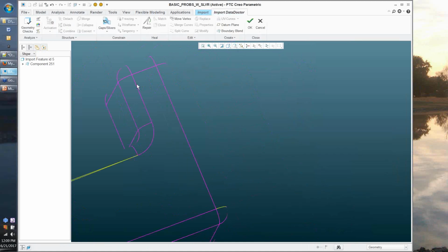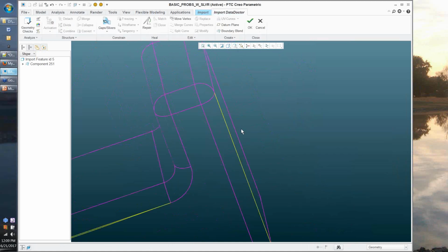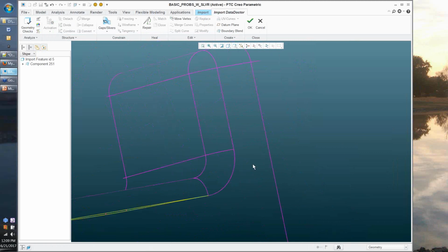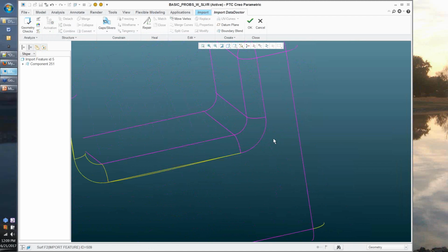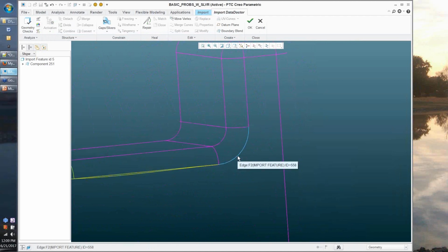And you see here, sometimes when you do it this way, you get more for your money. We didn't declare this gap down here that was present on the model, but it was repaired as part of that process. This is why I encourage people to kind of work surgically and simply and not try and throw the bucket of repairs at everything at one time, because you'll generally have a better process walking through that way.